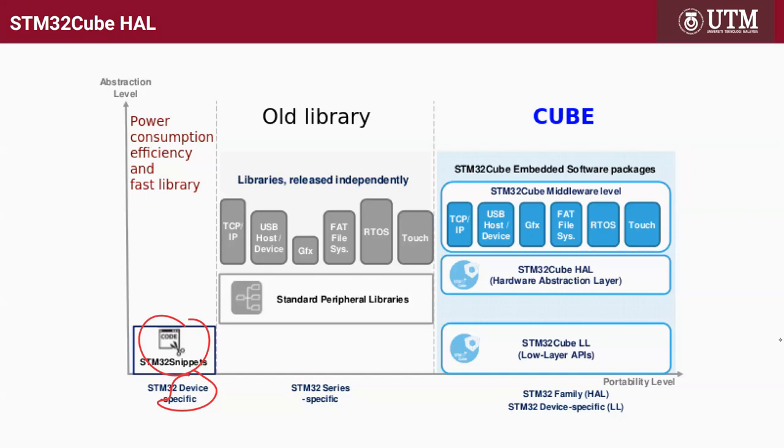And it's possible that you also have some libraries from last time. And now ST Micro, they try to merge all this. They want to upgrade to the abstraction software. So for the abstraction, there are 3 layers: the middleware, the HAL, and then the low level API. The low level is the one that is really doing the work, and maybe GPIO should be quite efficient because for GPIO there's nothing else to explore. So when you install the HAL, you have to make sure you have all this, then you can generate the